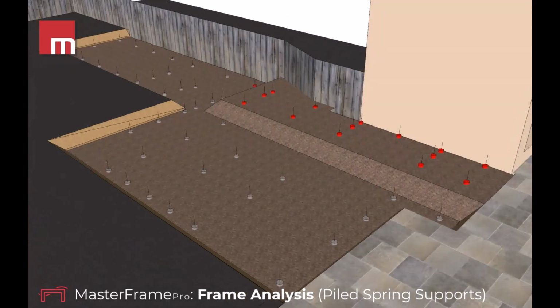So starting at the substructure and looking at the foundations, the local site investigation showed the ground to be soft clay with a high water table present, reducing the allowable bearing capacity of the soil. SPT values were ranging from 5 to 8 or so within the first 3 meters. Groundwater was encountered about a metre and a half below ground level. So shallow foundations were opted against, and as you can see, the proximity of the neighbouring property meant that excavation depths for the installation of the new foundation were to be limited to avoid undermining any existing foundations.